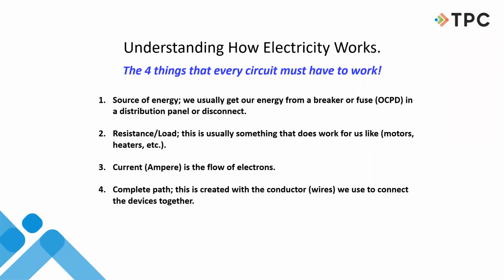Then we need to know the current flow. What should it be? When it comes to motors, it's always very nice to know the running amps. What's the running amps on that motor? So when that machine is out there doing its work at 100% of whatever it's supposed to be doing, I've checked that motor and I've written down what those running amps are. Those are very important to me when I'm troubleshooting or even just doing maintenance, to know what that should be. So I've got a motor that's good for, let's say, 15 amps and it draws 12.5 when it's doing its thing.